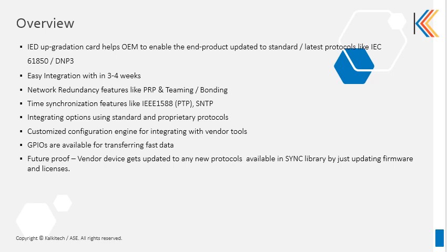So multiple server protocols can be there, like 61850, DNP3, 104 can be supported together, or any new protocol that we are coming up with or launching in later years. These things can be easily supported with just a protocol update, with a firmware update. So this is completely future proof. For any future requirement of the protocol, this also will be very much suited for the device.